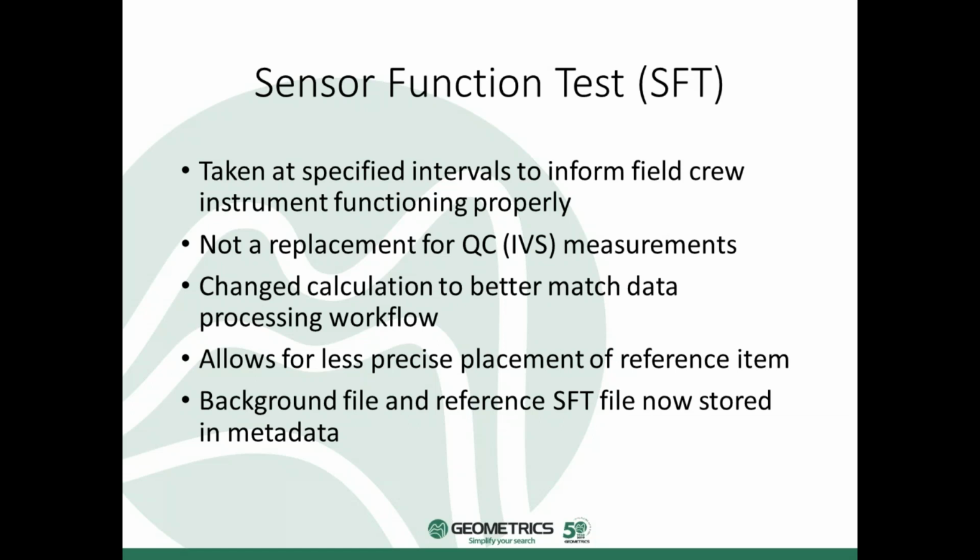What the field crew will do is place a standardized item, a metal pipe, on top of the sensor and make a measurement, and the software will give them immediate feedback saying sensor function test passed, go ahead and continue the rest of your acquisition. The idea with the sensor function test being that the field crew doesn't waste a day or half a day of collecting data with a faulty instrument.